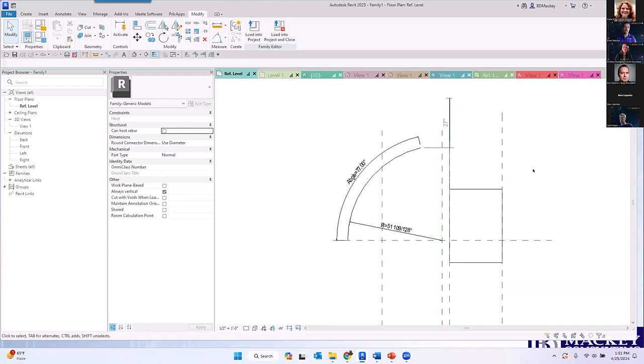My old RFTs, I could still rename and go back and forth, but I tried doing the out-of-the-box Autodesk one a month ago, with Paul Aubin, and we were not able to. We asked Aaron Malik, he was not able to either. So something happened, and I need to get with Autodesk to figure out what that is. But if you wanted an old family template that has some of that in there, just email me or join us on Revit Radio, and I will send you my family template, which has some of those things set in there. That will also let you rename it to RFA, RFT, and back and forth.